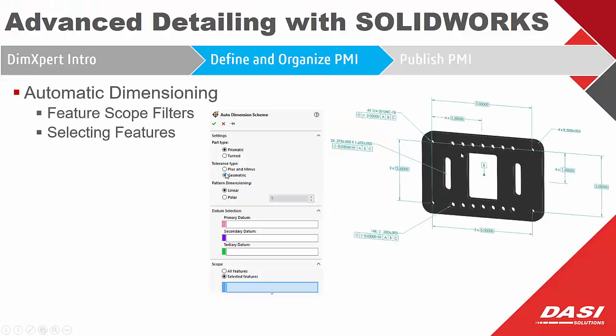Let's go through our next example, which is an auto dimensioning scheme for GD&T to support the ASME standards. Here again, I'm just going to use a prismatic scheme for a milled type part and geometric tolerancing. This time I'm going to be more specific on how I select my datums. I'm actually going to use width features or geometry to define the center of the part, as opposed to using datum planes.